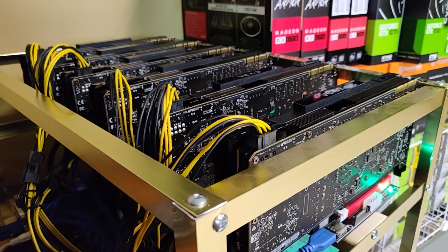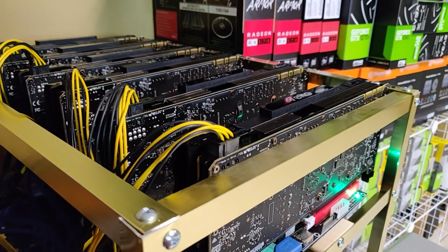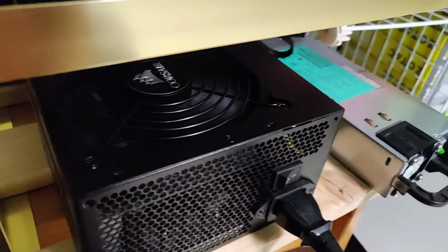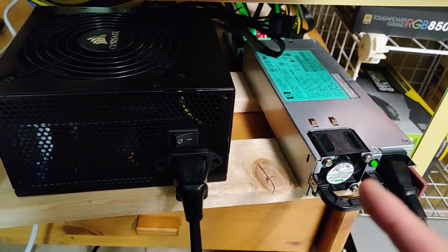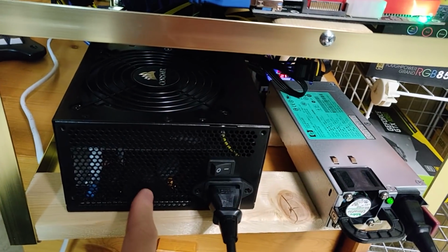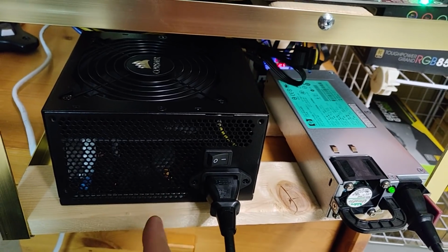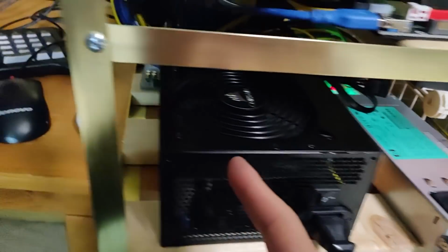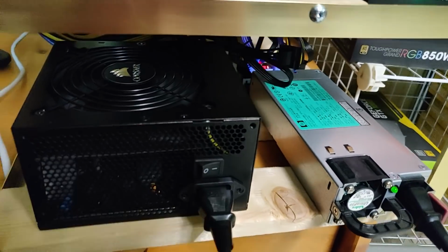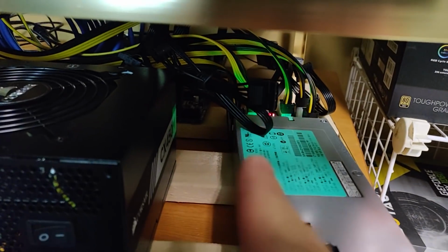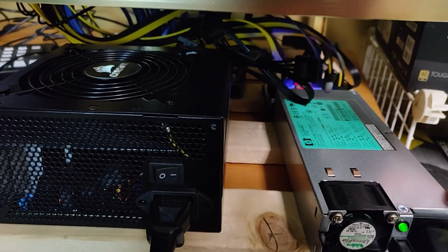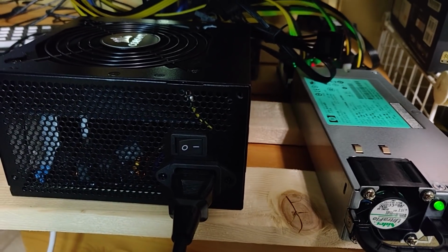I thought it would be about 120 to 130 watts, but for some reason the watt meter is actually showing a lot more power consumption. So I'm curious if it is because I have 2 different power supplies. I wonder if this bronze rated PSU is actually utilizing more power, even though it's only plugged into the motherboard and the CPU for power, as well as the SSD. And then it has the daisy chain connector, the 4-pin, which goes into the HP server power supply. So I'm not sure if that's drawing maybe a little bit extra power.